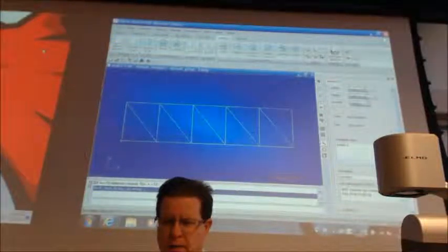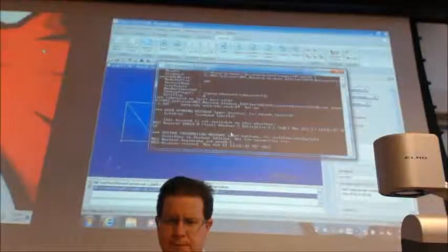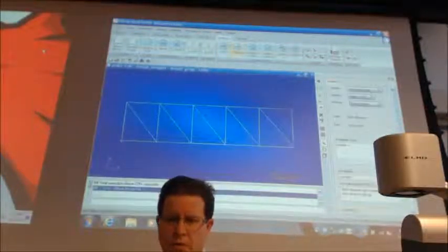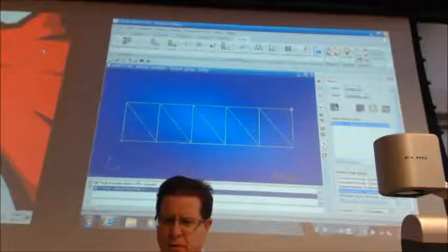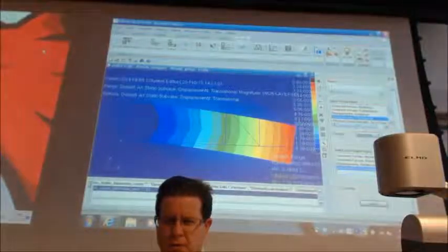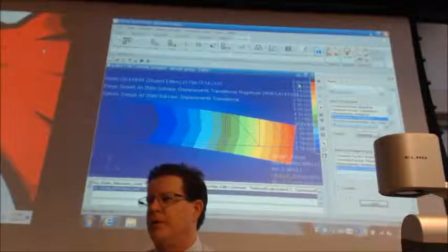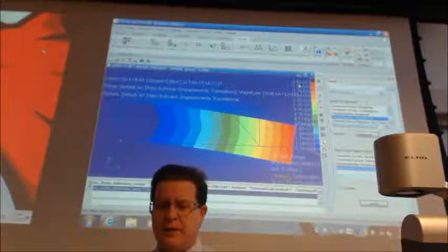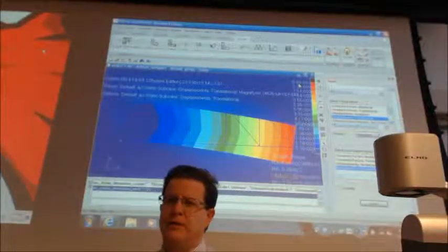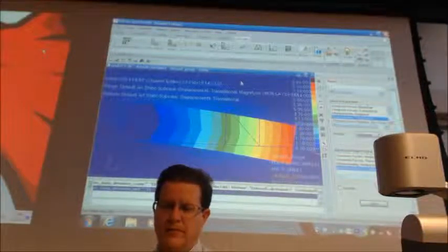Now that I've created that, I'm just going to write over top of everything. Say apply results. So if I go do my deformation and apply, now I got 8.93. So that's pretty close to what we calculated by doubling the number of nodes on the triangle. We didn't even increase the number of triangles, we just increased the number of nodes on them. Okay.